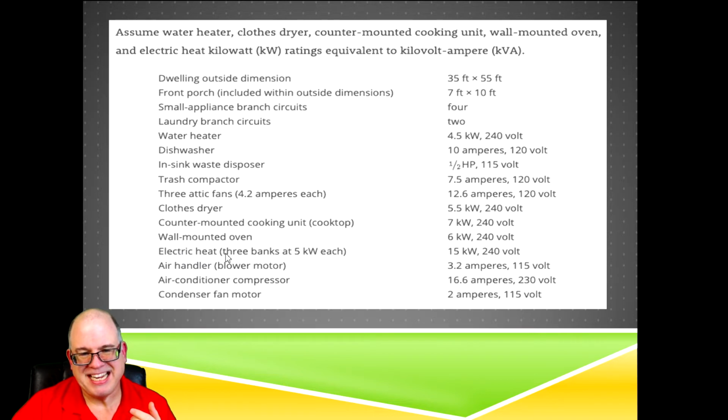We have electric heat. Okay, 3 banks of 5 kW heat. And I will tell you up front, no matter how you design it, this air handler utilizes an application where, in many cases, if it was a heat pump, then the air handler would also be associated with what we call supplemental heat.